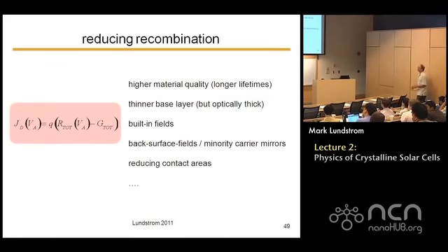So how do you know... the whole objective in solar cell design is to increase the generation rate, absorb as many electron hole pairs as you can. So you do that by minimizing reflections and by trapping all of the photons in the structure. And then to minimize the recombination rate. The smaller it is, the better off you are. And you minimize the recombination rate by getting as high a quality material as you can, with very long lifetimes.